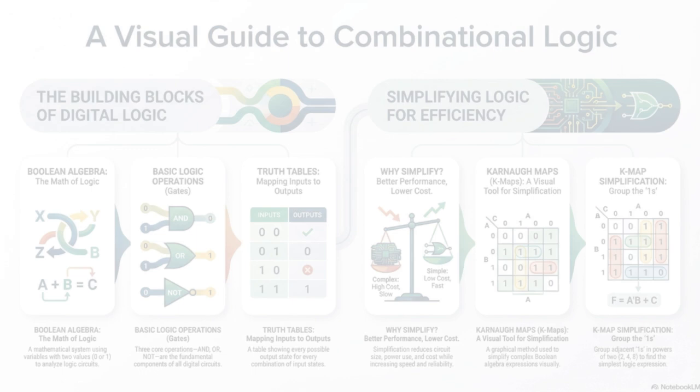Makes sense. Now, beyond individual gates, engineers use prepackaged complex logic blocks, these medium-scale integration, or MSI, packages. Let's run through the most common ones. Okay, let's start with a decoder. Think of it as a translator. It takes n inputs and gives you up to 2 to the n outputs. It interprets an input code and makes sure only one specific output line becomes active.